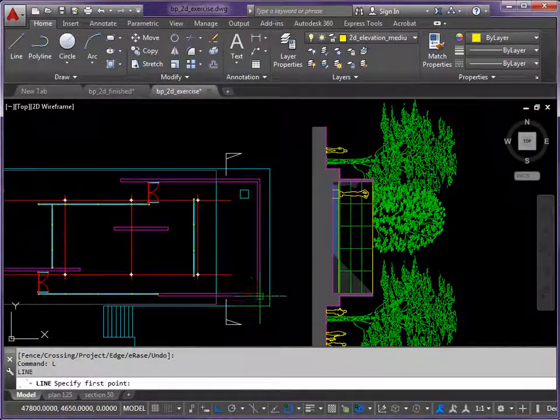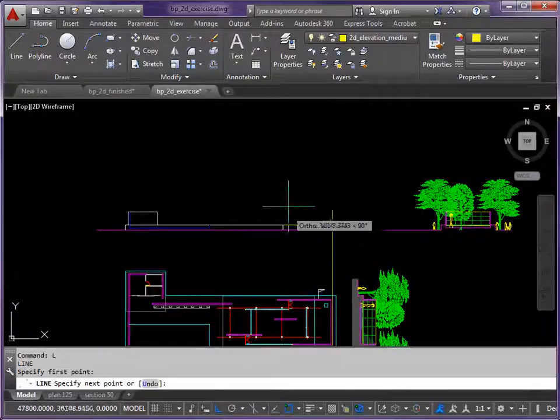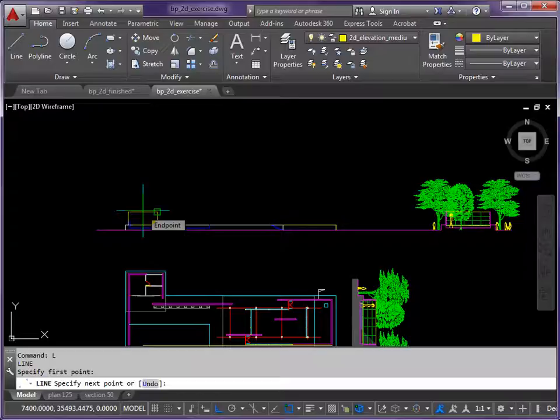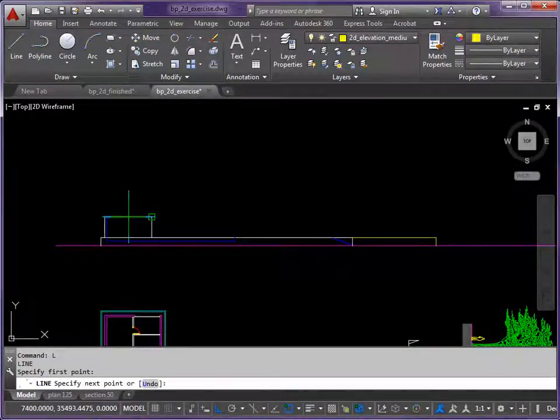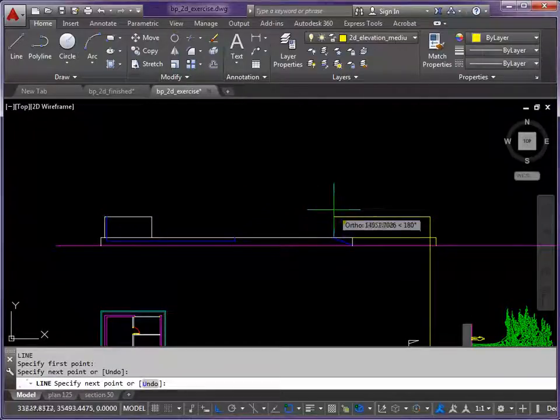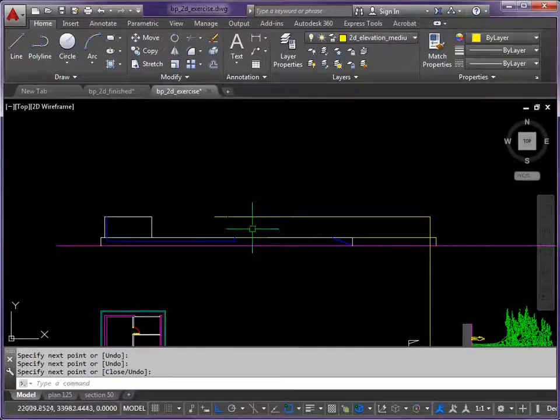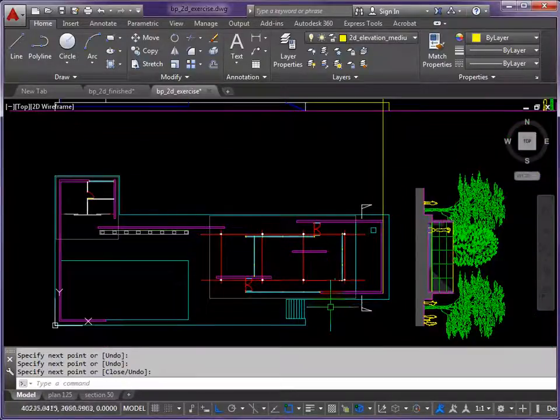We now need the walls, and this is in the same way. I want to take this line to the same height as this line, so I take my cursor over this line, tap the tab key, the perpendicular icon has appeared over on the right hand side, left click now and drag across. Just drag this line right across because we're going to need it in a few places.